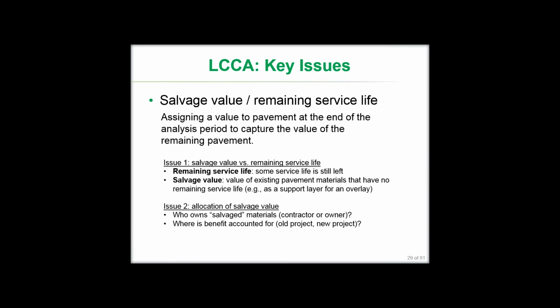Salvage value versus remaining service life. It's really this idea of salvage value is assigning a value to a pavement at the end of the analysis period to capture the value that still remains in that pavement beyond the analysis period. So there's a couple ways to do this. The first issue is just a salvage value versus a remaining service life.